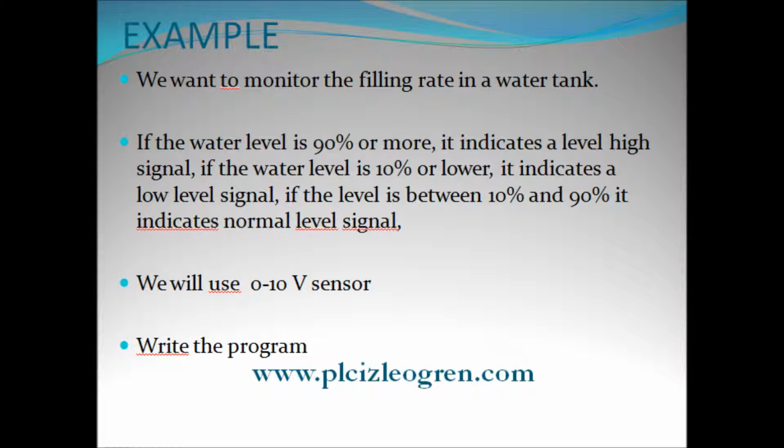Let's assume your operation pressure is between 10 and 90 bars normally. This is a random number. Normally it won't be that high. Normally it's between 85 and 90 bars. But we will say 10 and 90 for the sake of this example. If there is a pressure level between 10 and 90 bars, which means your pressure is somewhere between 10% and 90%, a pressure level normal signal will be directed to where your operator is based or where your command center is based.